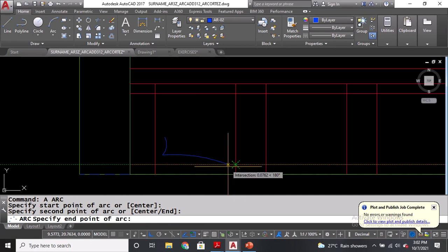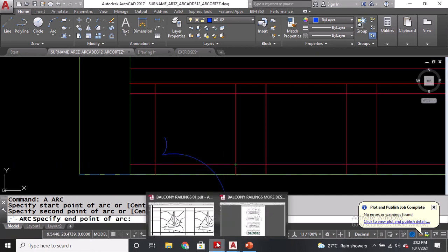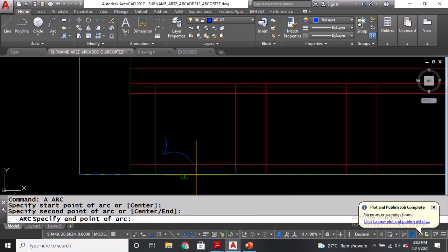Or somewhere. Saan ba siya banda? Okay. Yan. You see the intersection. Pwede po doon. Diba earlier we have activated intersection o snap. So, ayan. Nagkaka-intersection tayo doon. And as you can see, yung reference line, yan po yung tinatawag nating object snap tracking. It's also very useful drafting tool. It can make things easier to get done.